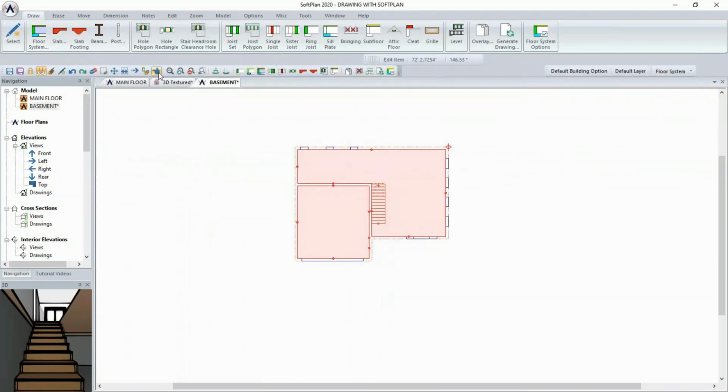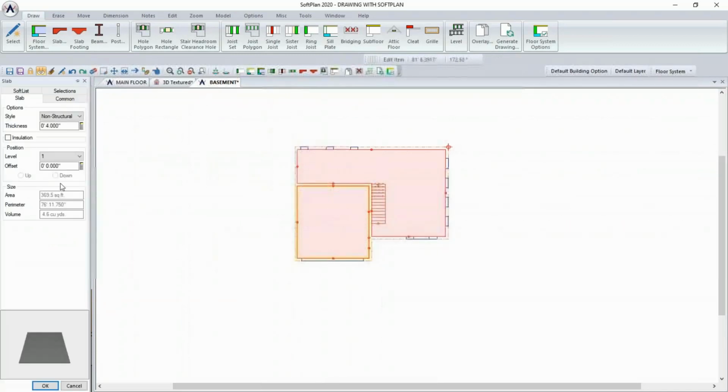I'm then going to review the position of the garage slab. So if I edit the middle of the garage slab, we have a tool in there called offset. That's the vertical placement up and down of any object. So when I drive my car into my garage, I don't want to fall down. I want to then raise my garage slab up 7 feet such that the top of the slab is flush to the top of, or I guess the bottom of the garage door.